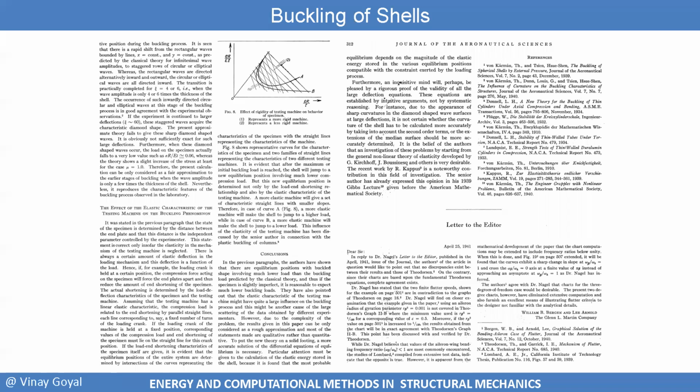And the paper goes through a lot of information about testing of buckling, and in this paper they show how the buckling predicted by classical theory tends to be smaller than what you will get from testing. And the reason is because you have imperfections in cylinders that could become a problem. I have a whole video on buckling that goes through that. I encourage you to look at that. It is under the advanced aerospace structures class. I have the video there.